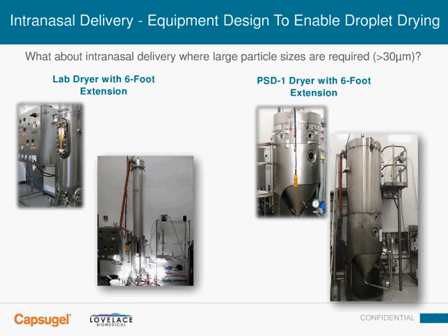So here's where we actually do need the larger chambers. If we need to now dry particles in the 20, 30, 40 micron range and purposely minimize fines, we have to make much larger droplets, which require a much longer residence time to dry. And so here's just some of our chambers modified to allow for some of these types of formulations.